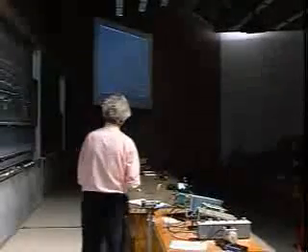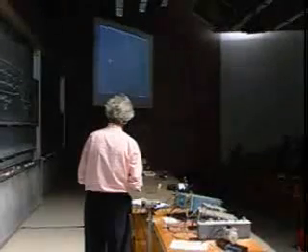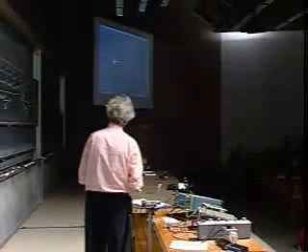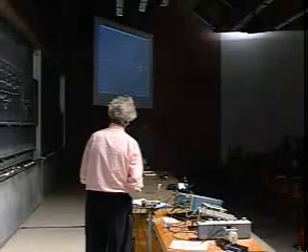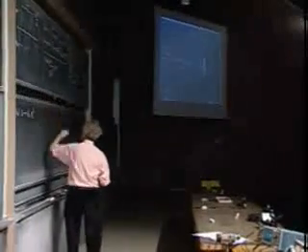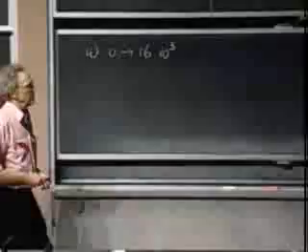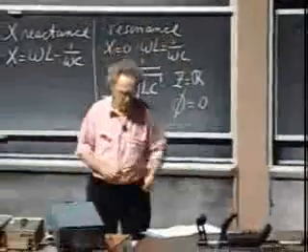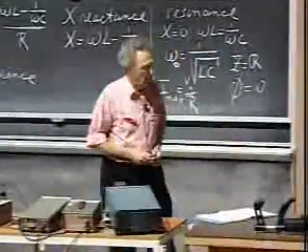And I go very slowly. Now omega is 0 here. Omega goes up. I go through resonance. And omega is here, the value, the 16,000 radians per second that we had here. And it sweeps back and forth between 0 and 16,000. So you see a dramatic increase at resonance.